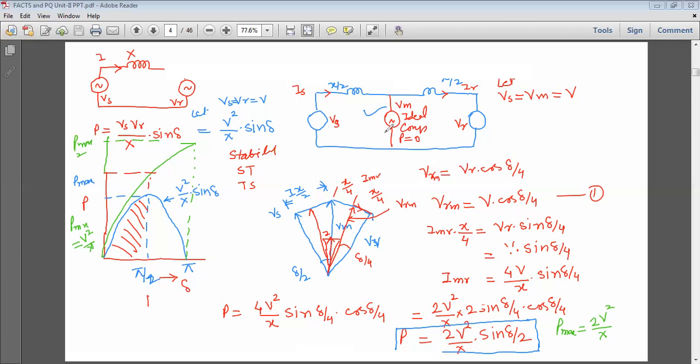Because the voltage sag at the midpoint is maximum, if you inject current in phase quadrature with the line voltage, it is going to supply reactive power or consume reactive power, with a capacitor or inductor connected respectively. Hence we can improve the transient stability, steady state stability and power handling capacity of the transmission line. And this is the main objective of the FACTS controller.